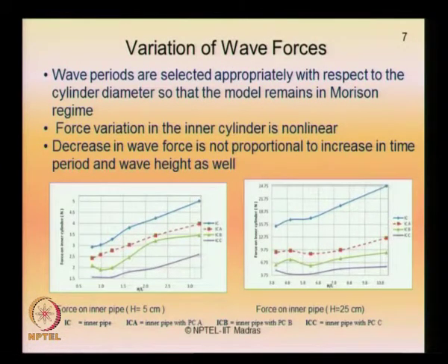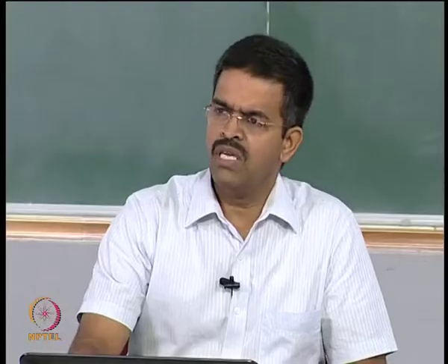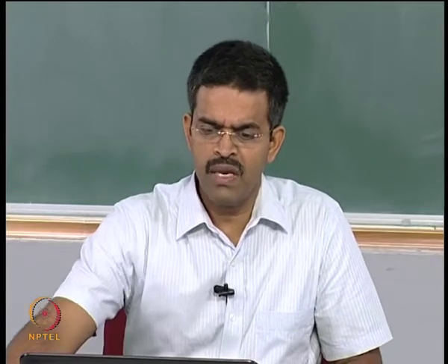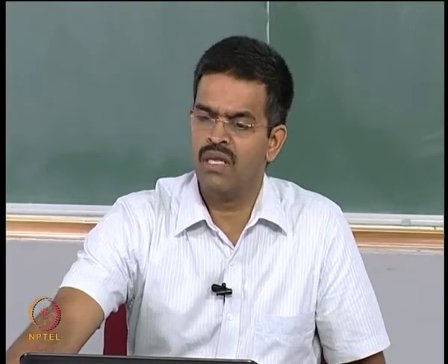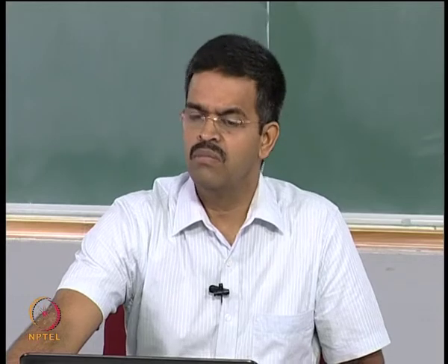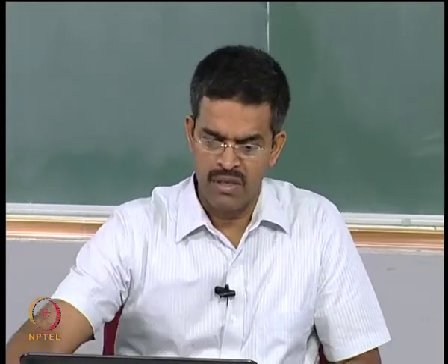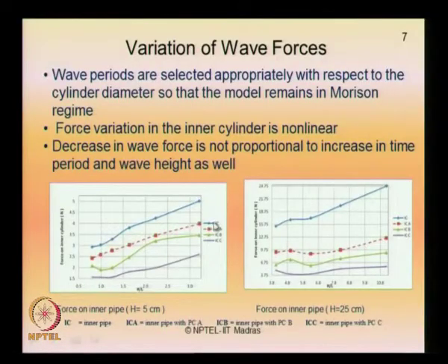If you also look at the variation of wave forces on the inner cylinder because of the influence of perforations, the wave periods are selected appropriately so that the cylinder is, of course, in the Morison regime. The force variation seems to be non-linear. The force on the inner cylinders seems to be non-linear.